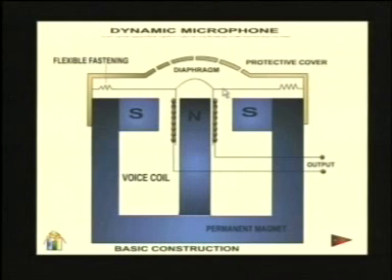metal sheet, and air pressure is exerted on it. This diaphragm is a metal sheet and accepts the air pressure from the outside, so that this metal plate can move downward and upward. And it has a flexible fastening. Whenever the diaphragm moves inside or outside, the fastening stretches or acts as a spring, such that it always keeps the diaphragm in the center.